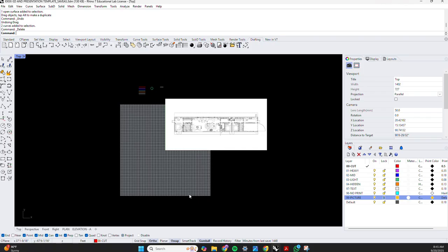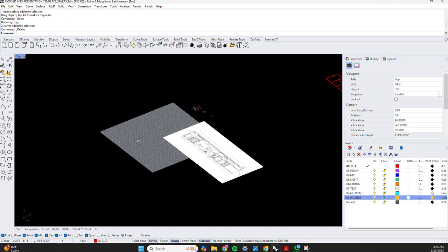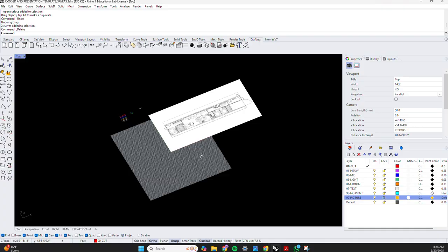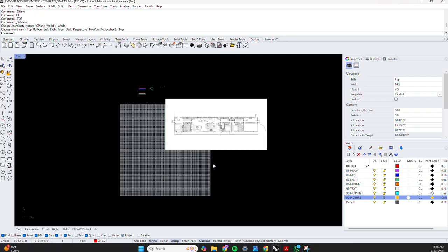top view, but we can hold Control and Shift and right click, and, of course, Rhino also works in 3D, and you notice down here on the world grid, the z-axis pops up, which is this. The x is exactly 90 degrees and perpendicular to the y. Either of these horizontal planar axes are 90 degrees and exactly perpendicular to the z-axis. We can see that if I go back into that top view, by my hotkey is TT,